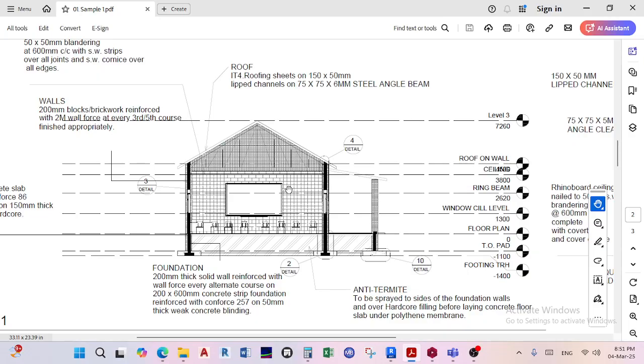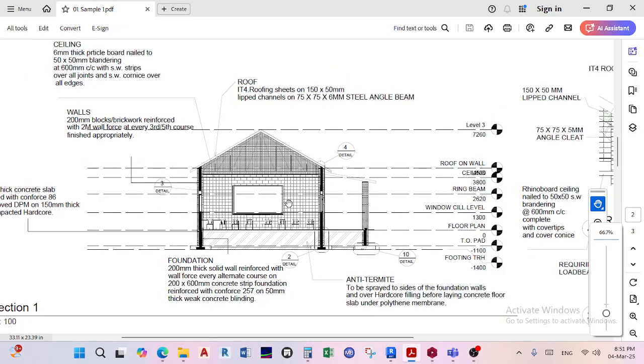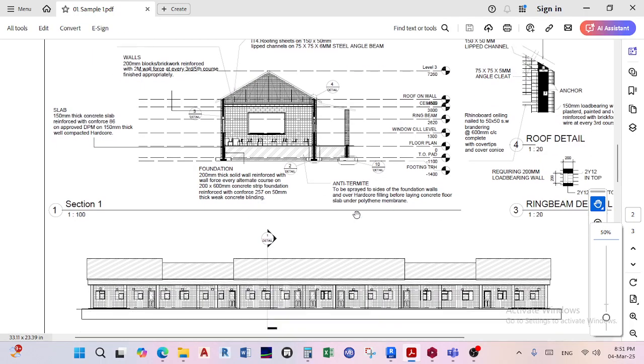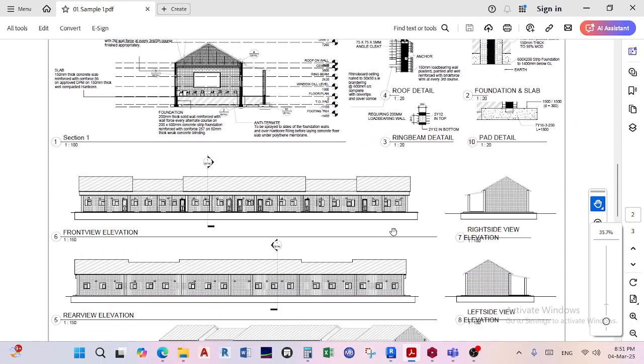And then what else? You design the section, then you calculate the area of steel, and bear in mind the size of the column will affect the reinforcement that you use. You cannot have a 200 by 200 and use Y16s. That's too much steel for that section, meaning you have to increase the section. You probably need maybe a 300 by 300. You can go back to your books and check them, and then you'll be able to confirm.